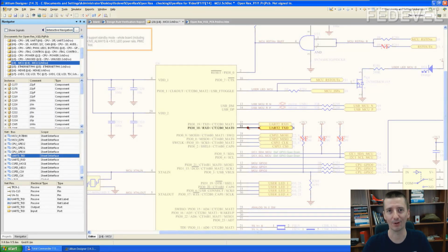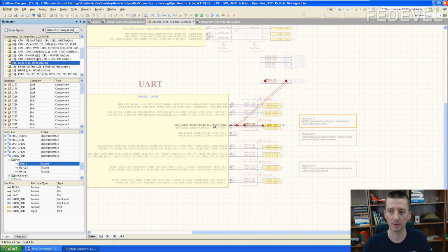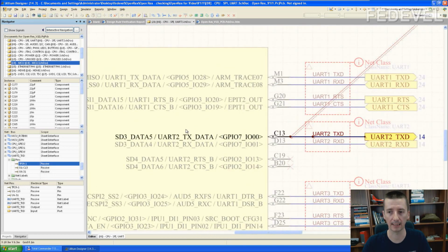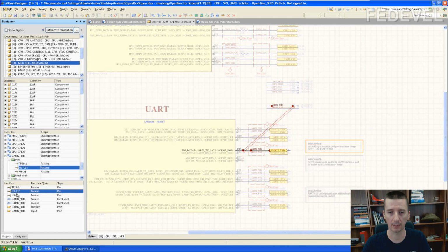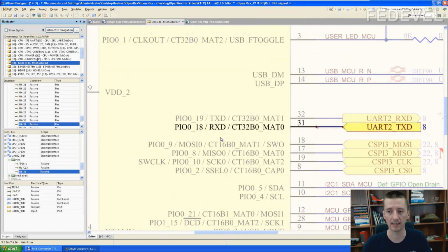What's very important for serial ports, for serial interface? Be sure you connect the transmit signal to the receive signal, okay? Because the microcontroller is going to communicate with the processor. On the processor, we have transmit data signal, which is connected to receive signal of the microcontroller. Sometimes you may want to also have a look if this really is input.